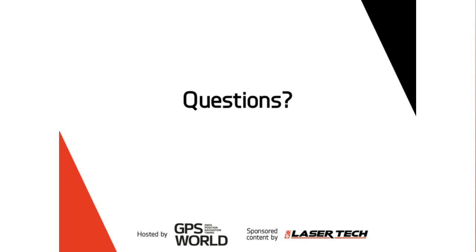Okay, cool. And do you have a solution for reverse tasks, such as finding the point on the ground, having the coordinate on the map? Yeah, that kind of sounds like a stakeout function to me, where you've got to put a mark on the ground and you have a coordinate for it. And our systems could be used for that. It would just depend on the app and if they had that function to upload a series of coordinates and put them out that way. So that's possible, yeah.